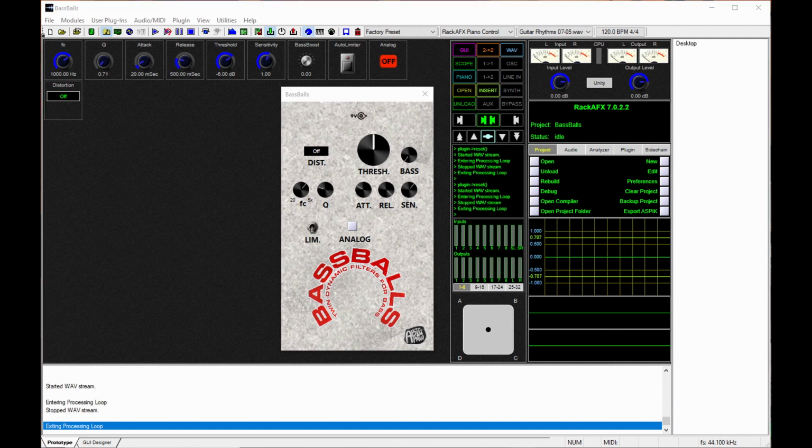One unique feature in this plugin is the Moog Ladder filter. Robert Moog's Ladder filter is a fourth-order low-pass filter designed specifically as an analog voltage-controlled filter circuit. As the Q is raised above 0.707, the filter's overall gain drops, producing a massive reduction in bass frequencies. The resonant frequency of the filter changes as the Q increases as well. If you need further information about this filter and the reproduction of the digital version of it, you can go down and check the link attached in the video.